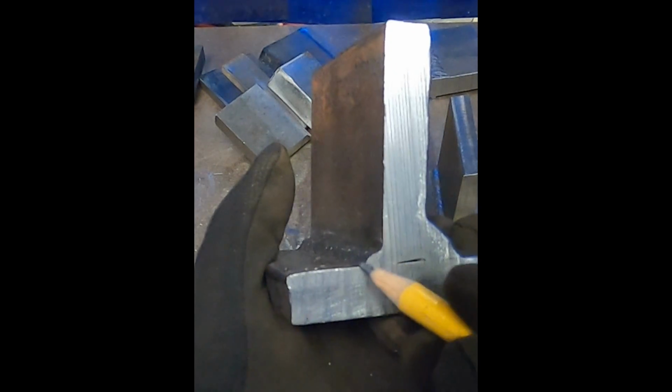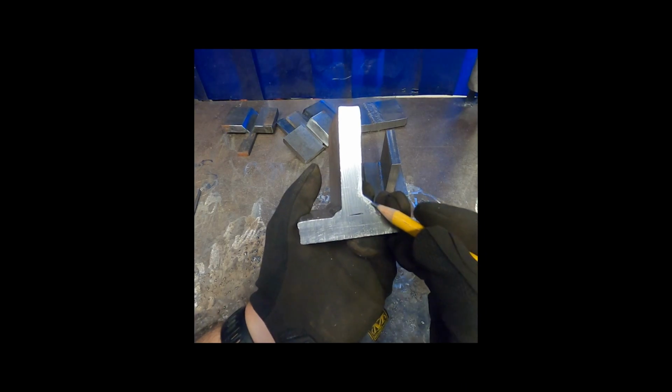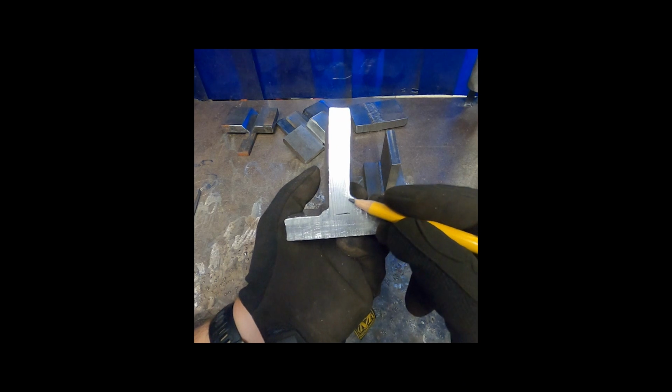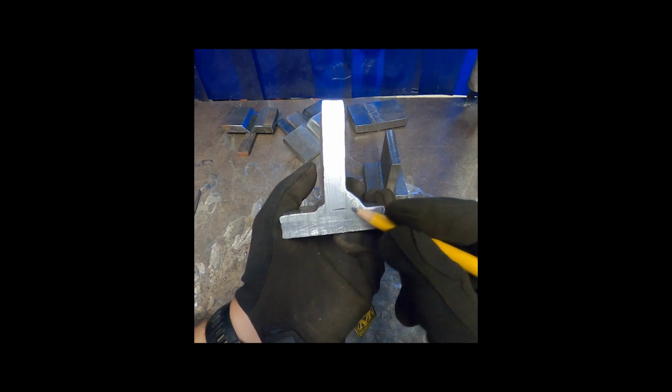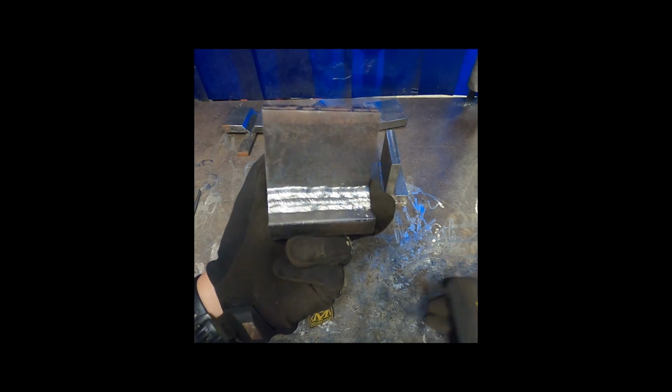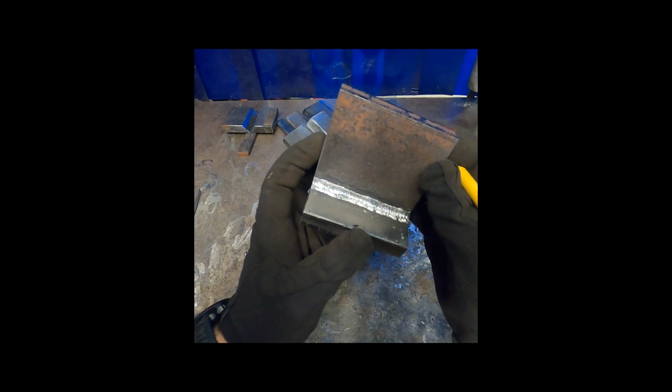And again, with this T-joint, I had a slight mishap in the fit up. So there is a gap between the two plates. So don't put all your focus there. Let's try and focus on the welds. You know, that was an oopsie on my part. And this is all just to kind of give you an idea of what looking at the throat, looking at the legs and the toes would look like in an actual welding setting.